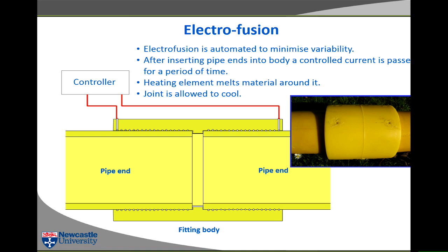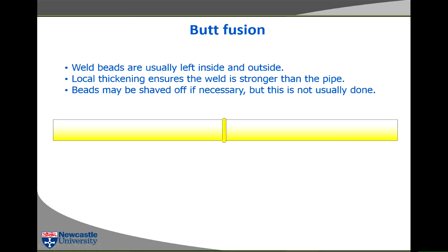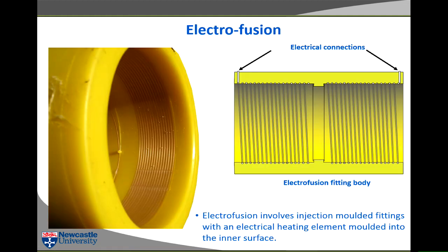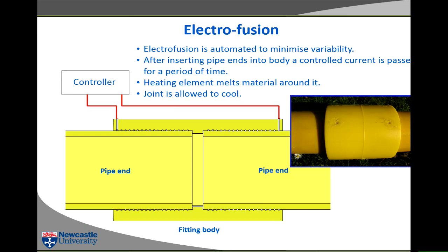Of course, the disadvantage of electrofusion is that it's very expensive. Having this additional socket with the electrodes on the end, with the wires on the inside, is much more expensive than a butt weld. So, given the opportunity, you prefer to do a butt weld, but in many applications, because of reasons of space, or because you might be joining pipes of different diameter or something like that, you have to go to electrofusion. So that's the electrofusion joint.